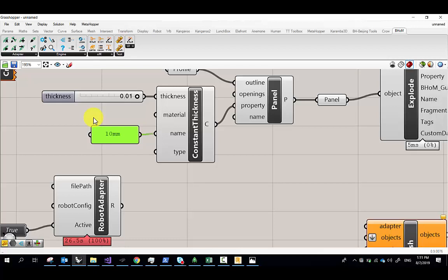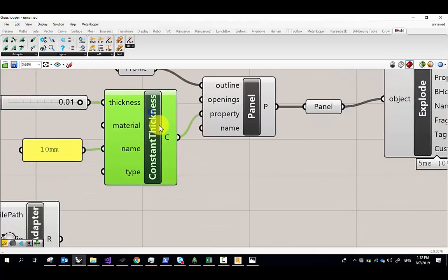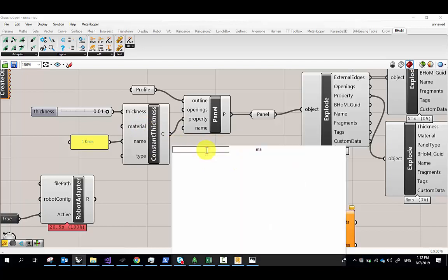We're going to create stuff here in Grasshopper and go over to Robot with it. So we're creating objects here. For instance, this thickness object, we've created it here. This panel object, we created it here. So how did we do all that? We did Shift Control B, right? Or the object one. So for material, if I do Shift Control B and I search material,